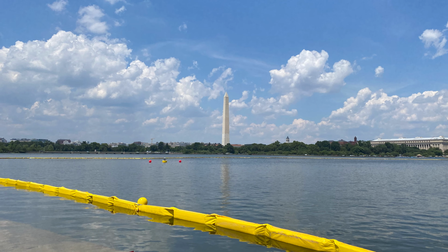The buoy outside the curtain or dredging area provides the most important data because it tells operators how and how much their activity is impacting the environment outside of the intended area. If the turbidity reaches a certain level outside of the site, operation should pause to limit the transport of sediment.